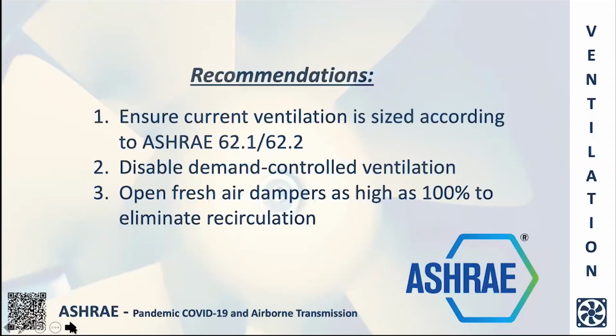Now, we have to put these things into context. If we disable demand controlled ventilation and we open fresh air dampers to 100% of what they're capable of, we may be causing some other unintended consequences, like being able or not being able to condition or heat or cool a space as needed. So it's important that we have a balanced approach to looking at all of these recommendations, starting with that ventilation.